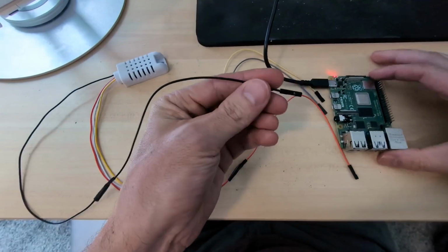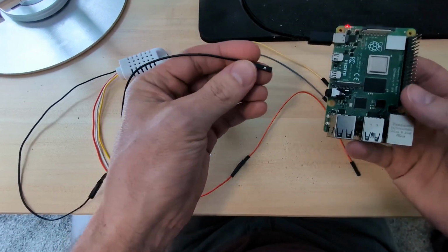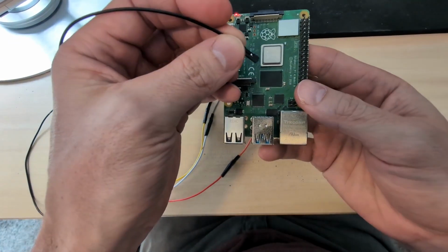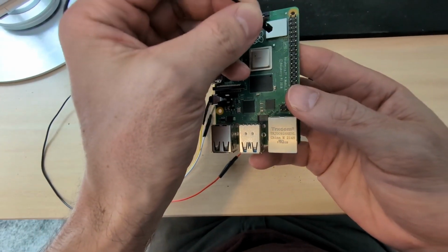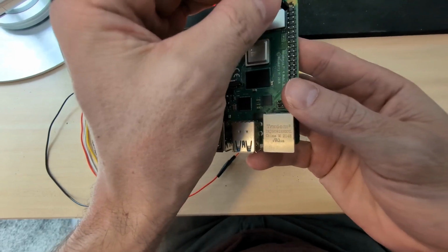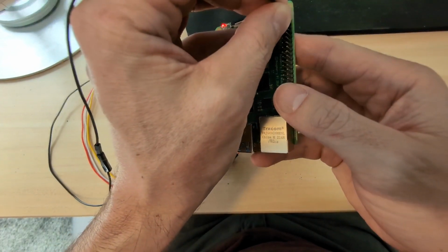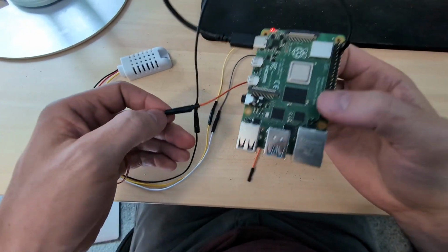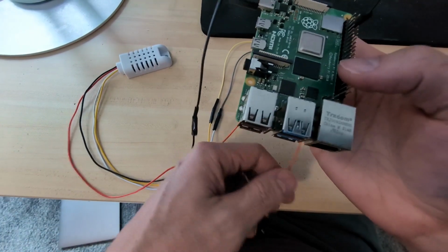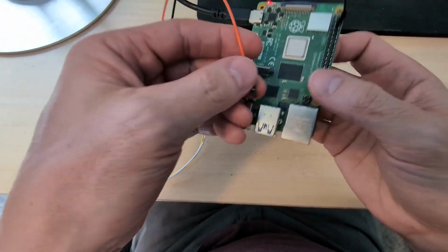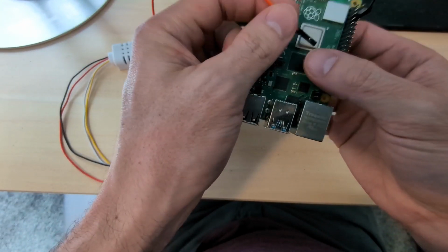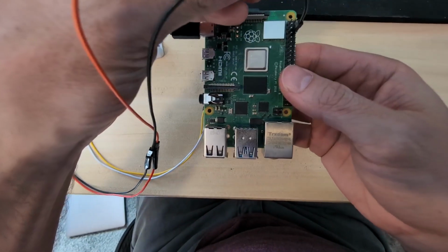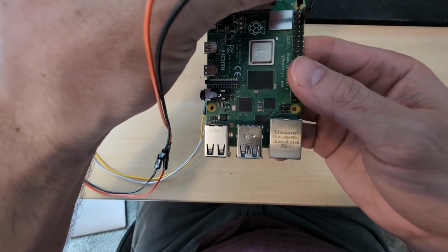Anyways, it's pretty straightforward. You just connect each pin to the appropriate location on the Raspberry Pi, and I can provide a diagram in the video, but ground is the third one on the right. Then we've got power. This device supports a pretty large voltage range, I think it's 2.15 volts up to 5.5. So I opted to go to 3.3, which is on the top left pin of the Pi here.